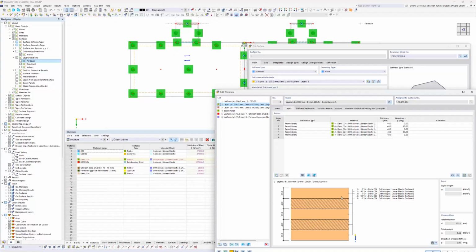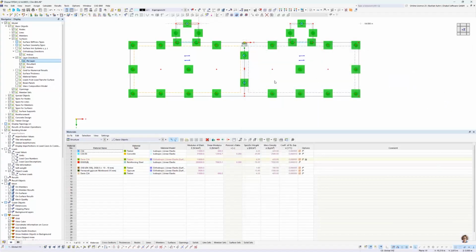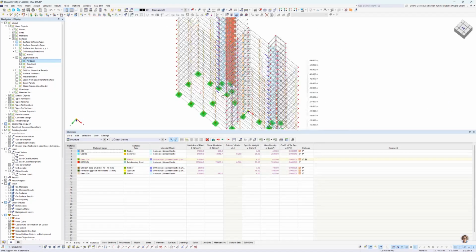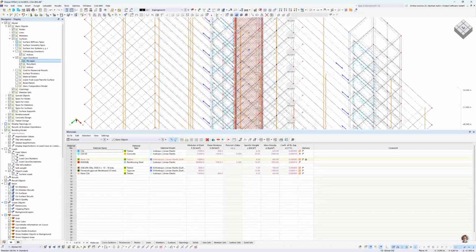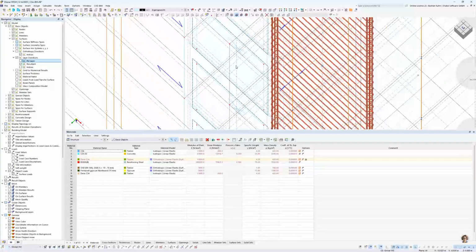We have to take a little detailed look into it. You see that the layers are oriented with the top and bottom plate, which gives you the main stiffness direction in global X. And that's wrong, because you don't want to orient it that way. And we also need to look for the walls. They are also oriented wrong in here.